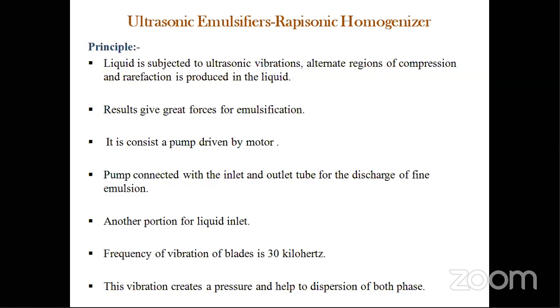In the construction, there is a driven motor, which is directly connected with a shaft, and the shaft is connected with a small blade or spindle. When this spindle vibrates, it creates sonication. Another portion is connected with a pump, which helps to inlet the liquid by suction and discharge the liquid by the pumping process.